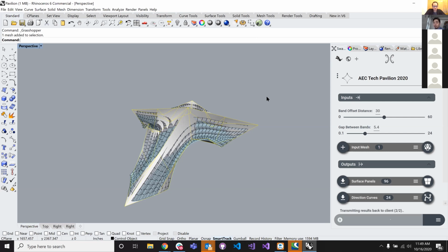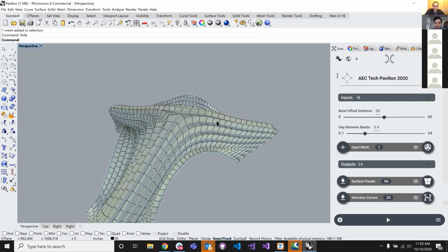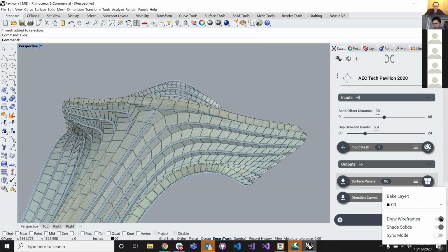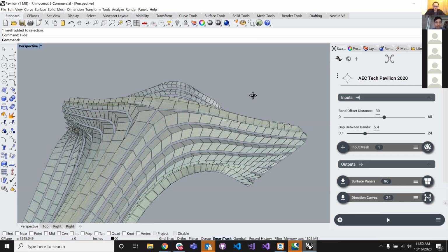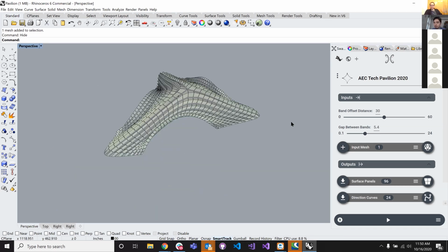Okay, so we already solved the definition and we're rendering the output geometry back. Okay, it was the 6,000 rivets. All right, so let me hide this and let me also hide the wireframes. So yeah, so now you can see that if I also hide the underlying surface and its edges, now we have the colors that were assigned in Grasshopper. And if we bake this, we'll also be able to see this.